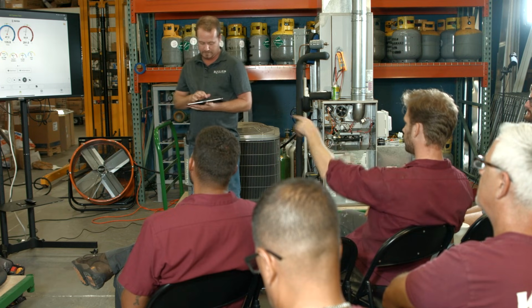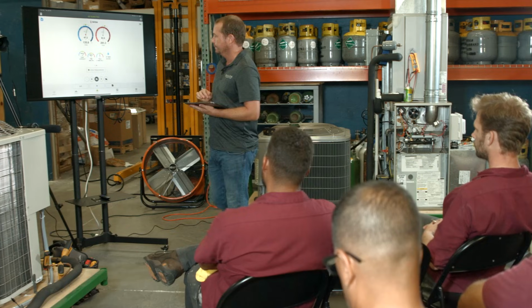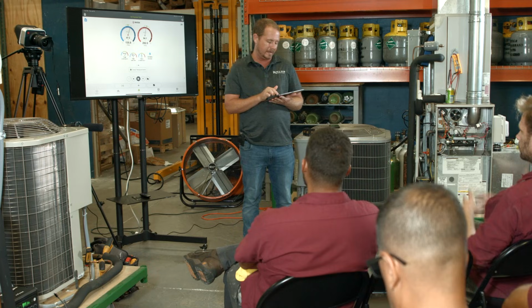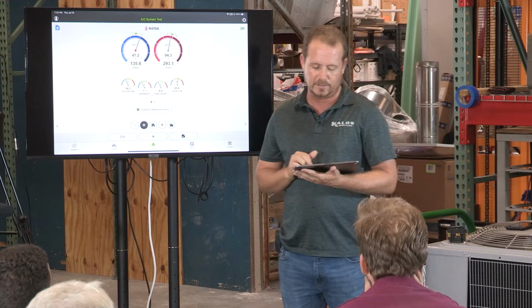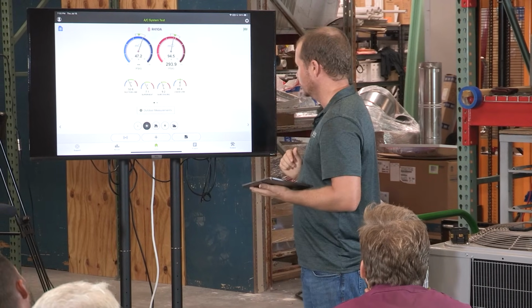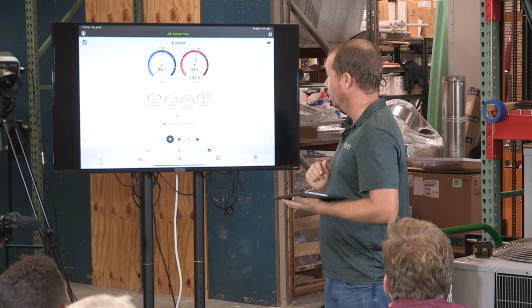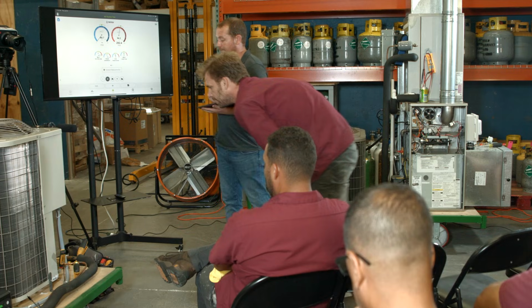But you see, 23.7 instead of 24. We are lower. But you don't want to overfeed your evaporator coil. If you get below your minimum stable superheat, you can lose control and actually dive to zero superheat, resulting in flooding. Flood back. Yeah, we're looking good. Subcool's coming up. Whoa. Our superheat just went really high. 114 degrees superheat?